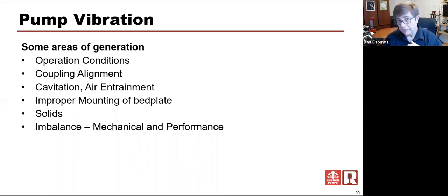One of the cool things about that pump that I said was sealless, that vertical that replaces the ANSI, is that all of those fits together all the way up and down that pump are all C-face rabbeted indexed fits. So there is no coupling alignment and there is no motor to shaft alignment. All of that's done for you. It's all fixed and mounted.